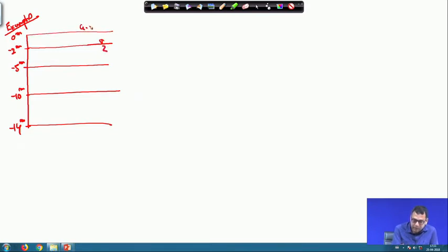This is the ground level. Okay. So, again here I am taking the phi value equal to 30 degree and unit weight is 18 kilonewton per meter cube. The same value I am considering here. So, my K1 will be 0.33, okay, like the previous one. Now, this is for the layer 1, and for the layer 2 I have changed the soil layer. So, this is 0 degree and C value I am taking as 25 kilonewton per meter square, okay, and unit weight I am taking 19 kilonewton per meter cube.